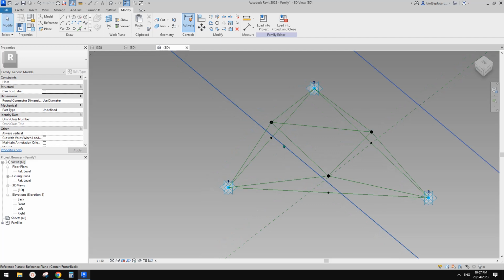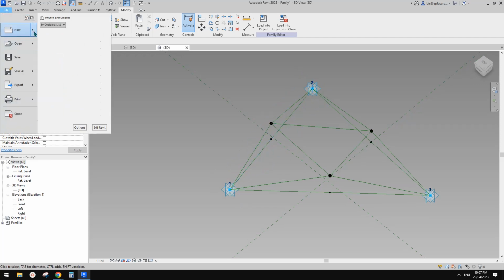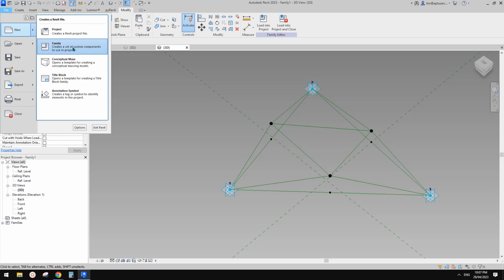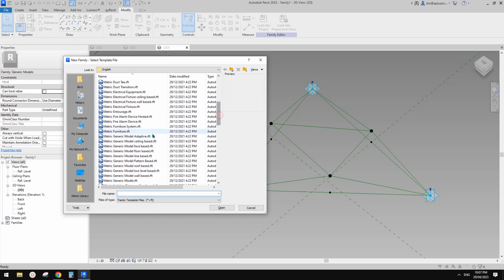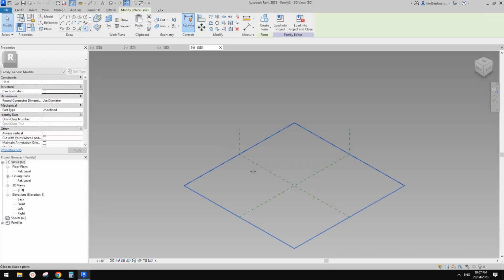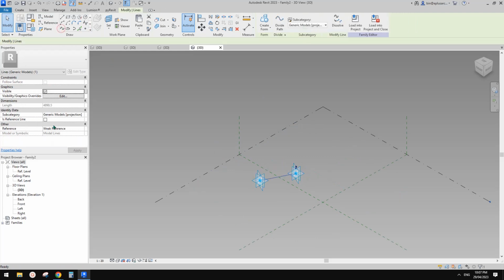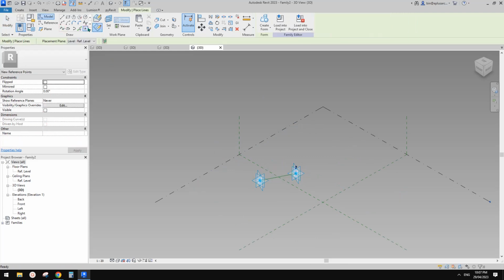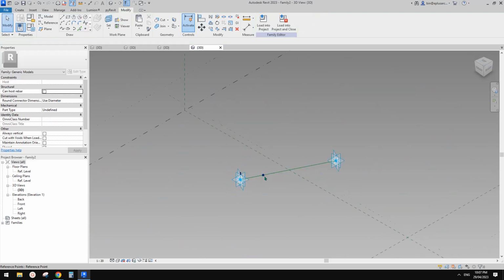The second step is, instead of trying to create a profile onto them, we're going to create an adaptive family, so it's easier to place. Okay, so it's easier to do it. So let's create another generic model adaptive. In this one, 2 points. Make adaptive, spline, make it reference line, and place point, draw on face, and just place it onto the reference line.